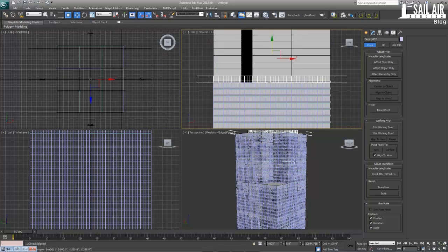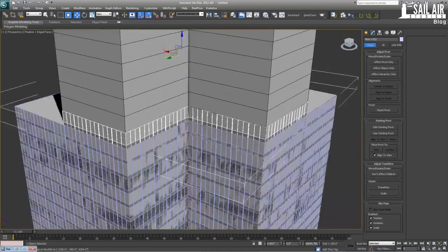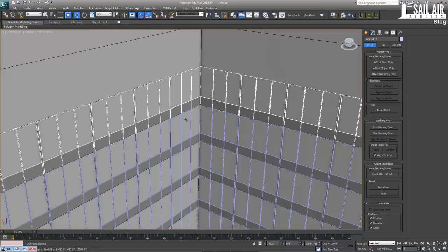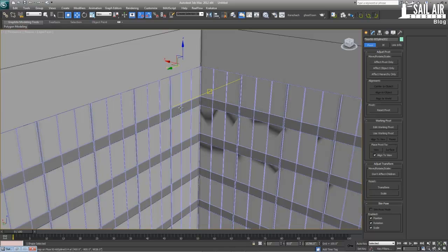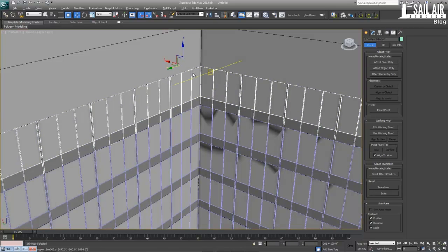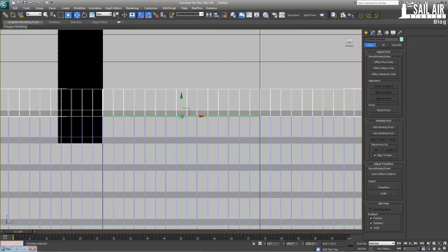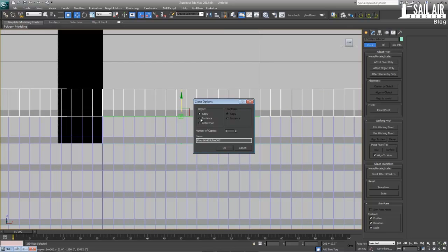So we'll select our floor, and we'll select our spline. I can somehow get that. Did I get it? I don't know. No, I didn't. Floor 66, 90 spline, and our RailClone object. And just copy this up, just like that. If you're not getting the pivot point right on the bottom of it, just effect pivot only, drag it down until it's right on the bottom of your objects, and then you can copy it out again.